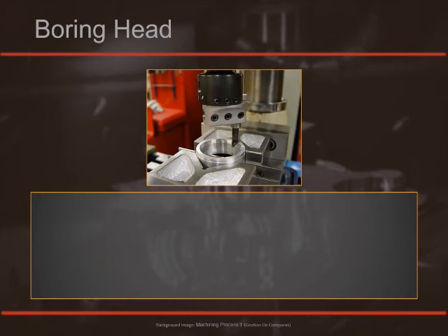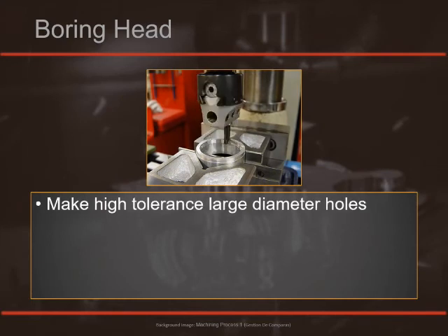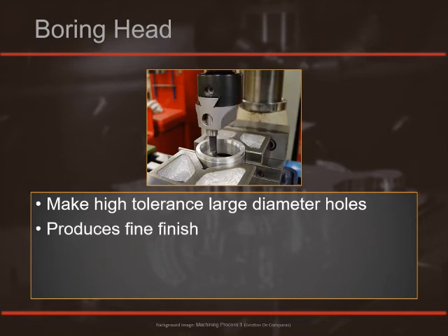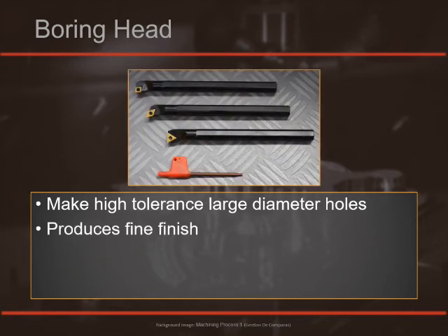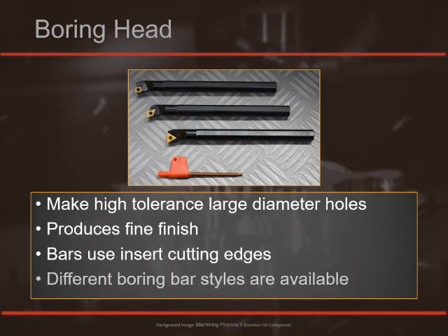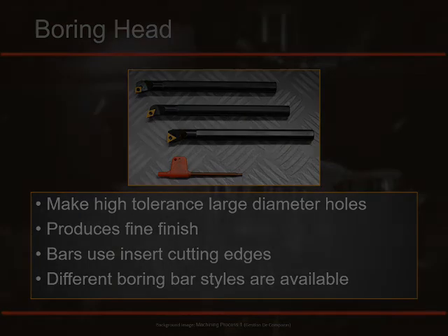Boring. Boring heads make high tolerance, large diameter holes and produce a fine finish, and the boring bars use inserts similar to lathe inserts. Different boring bar styles are available for different types of boring applications.